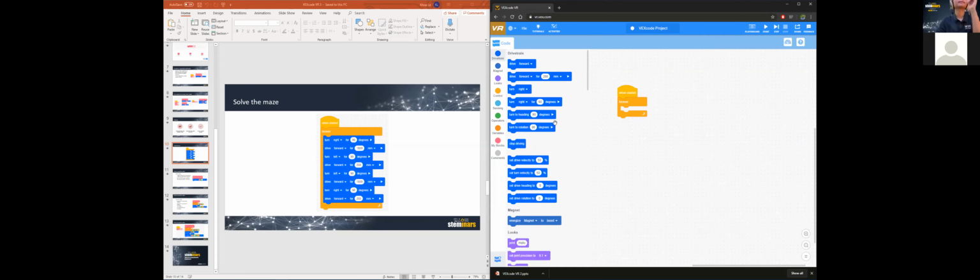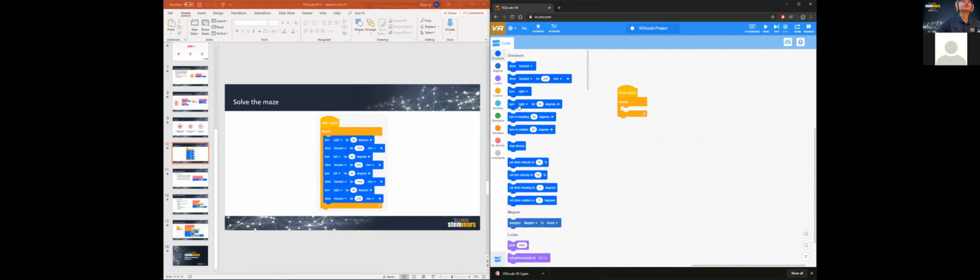Cool, let's do that. So first thing is to turn right for 90 degrees, no big deal. And we're going to drive forward. Again, each grid is 200 millimeters. So if I want to go from 1 to 10, I have to go 9 grids, which is 1,800. And then I'm going to turn right again. Actually, I'm going to turn left this time.